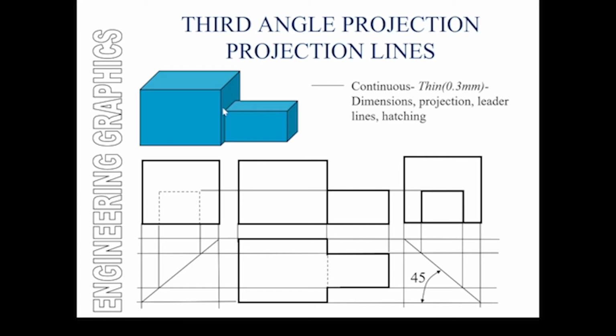However, you're going to see this space here, which is then shown as that. And exactly the same logic applies when you're looking at it from the rear end, where the detail doesn't really belong on that side. However, the detail is there, and you have to acknowledge it with a hidden detail, which is drawn using a continuous, no, it's not continuous, it's a dashed thin line. Also easily available in a good CAD package.